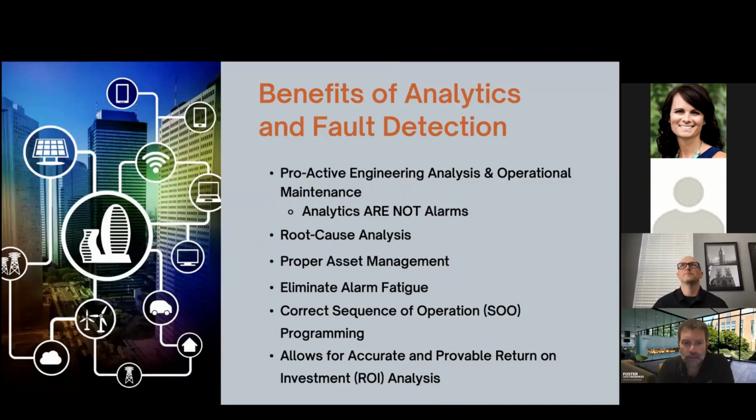Yeah, I mean, that kind of goes back to the root cause analysis, right? So we talked a lot about the proactive side, but the root cause, you're back to your VAV, you got a space that's warm, and it might alarm every day that the space is getting warm, but it's like, okay, why is that actually getting warm? Did they add different equipment in the room or what is going on there? And so on your BAS, you could be getting an alarm every single time it goes above that 80-degree mark.